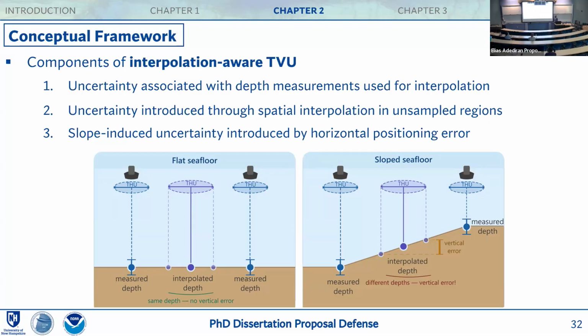One thing you have to keep in mind is that the azimuth of the survey lines would be different in a set line spacing scenario with multibeam or side scan than they would have been in existing single beam surveys. Those single beam surveys would have been run perpendicular to the slope, and in a set line spacing, they're probably running parallel to the slope. So you may have a different kind of physiographic environment that you're trying to assess.